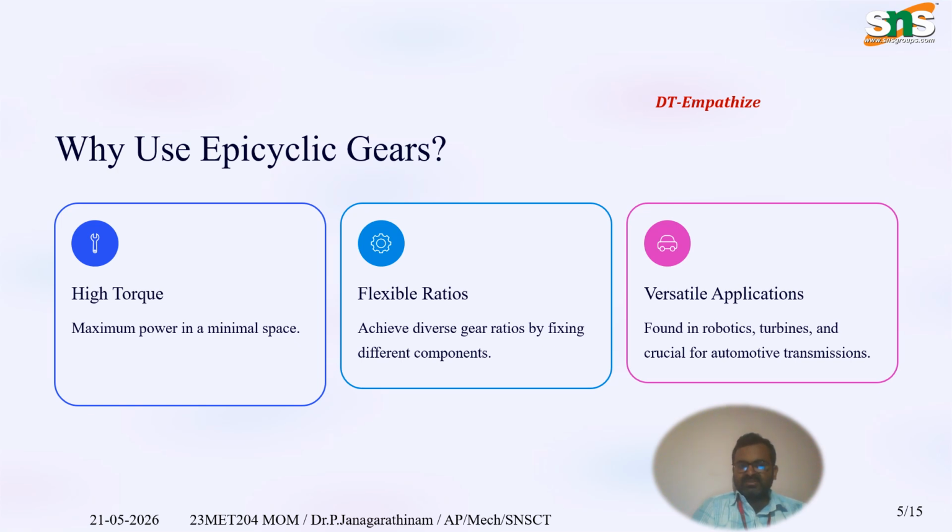So why use epicyclic gear trains? They give high torque and maximum power in minimal space, and they offer flexible ratios. You can achieve diverse gear ratios by fixing different components. They have versatile applications like robotics and turbines, and are crucial for automatic power transmission systems.